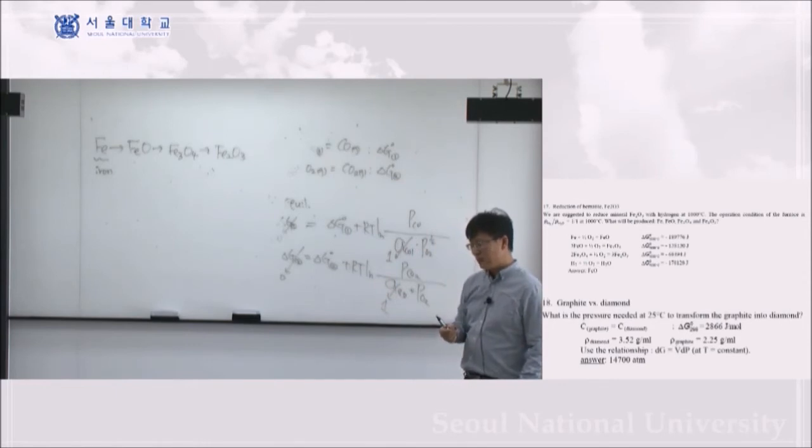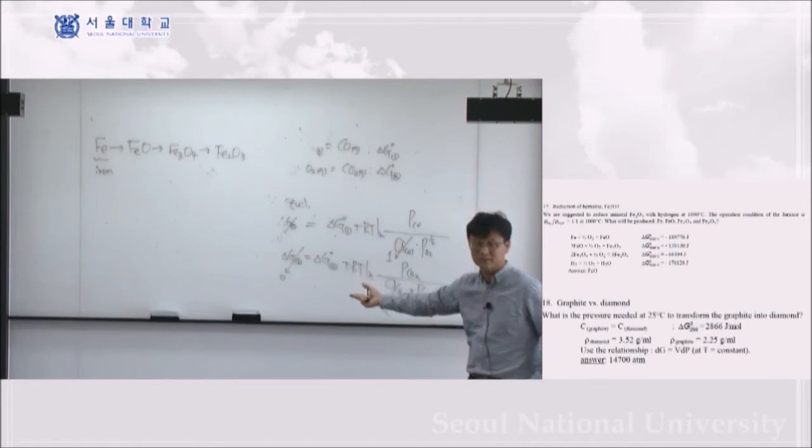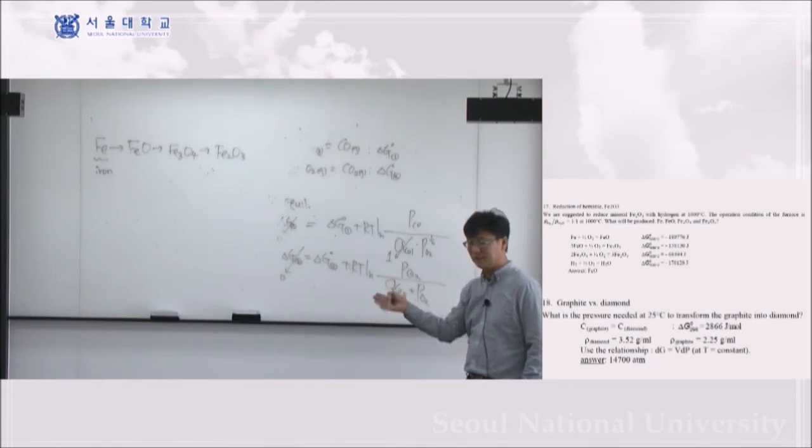And then by adding oxygen into the steel, carbon and oxygen react together and become CO gas or CO2 gas. In that way, carbon can be reduced to the certain range which we want to produce as a final product. Then we call that state steel. According to the steel making process, we define it this way: steel is a controlled composition product, and iron is just an uncontrolled composition product. So that's the more correct way to say.